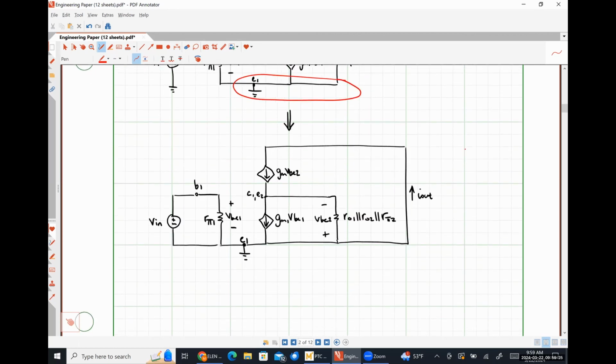How did you decide that the three resistors, like, put the others? Just, you know, that that's what's gonna make the math better, or is there kind of a system? If you move the R pi 2 and R naught 2 to where R naught is. Right. But how did you decide that? Because I could observe that I out is just going to be GM VBE2 if I draw it this way. So it's just what's gonna make my next step easier. Yes, 100%.